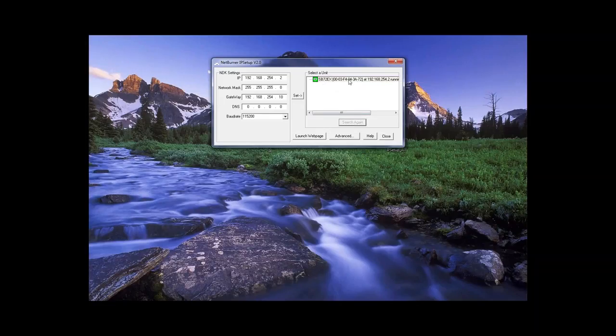So right now this is the VR Link I have connected directly to the IP on my transmitter. The IP address is 192.168.254.2, which is the default settings from Nautel. So now we are going to just log in using a web browser to the VR Link.